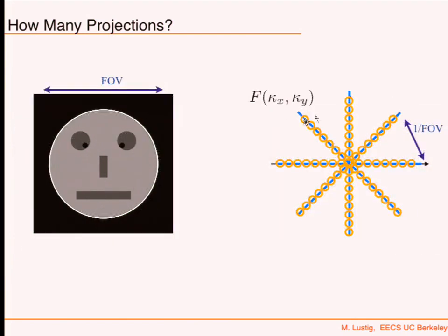Well, I'm going to effectively filter, right? There is a limit to how much sampling I have of the projection. I cannot sample it at infinite resolution. So I'm going to effectively have a finite resolution when I go to discrete time. So effectively, I'm kind of low-passing the projection before I compute the DFT.